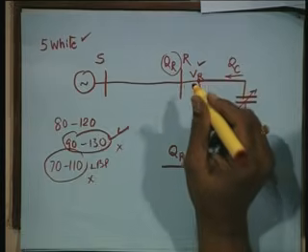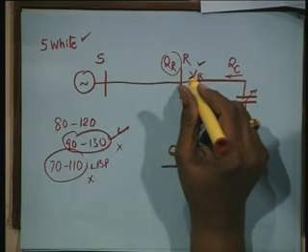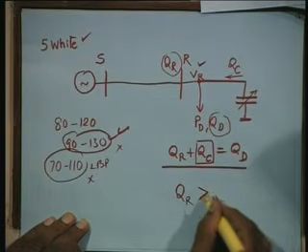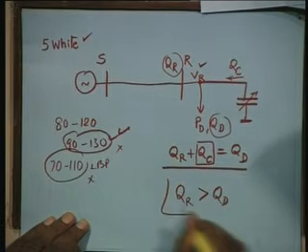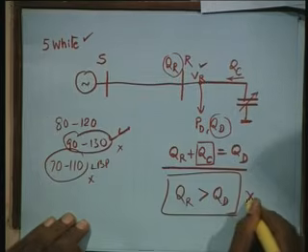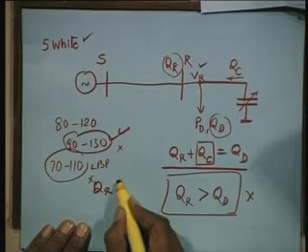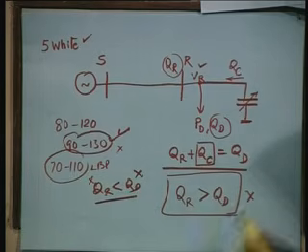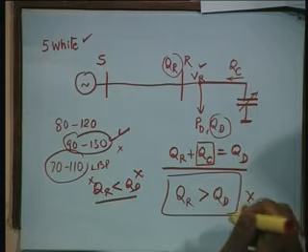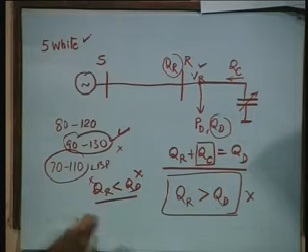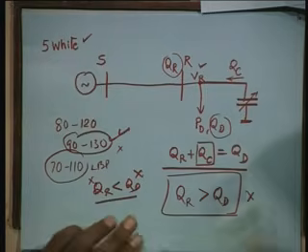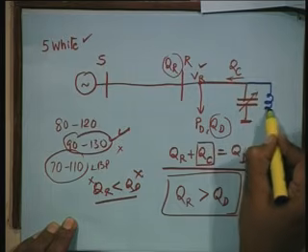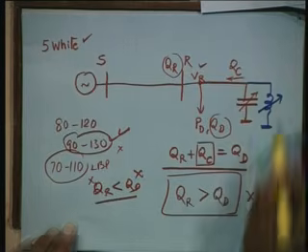And that's a Ferranti effect when there is a low load, light load conditions. You may have a condition when QR is more than QD. This is equally bad as QR is less than QD. Both are bad. If this situation occurs, what do you do? You do not switch off, that is not the way. That is like suicide. We have bank of inductors.